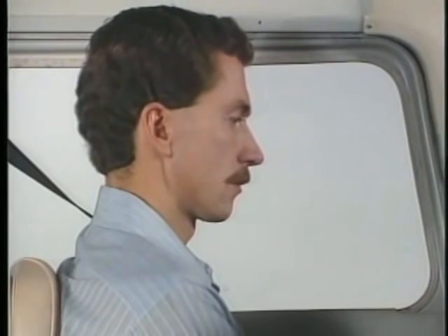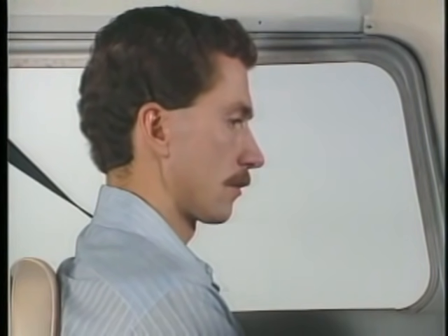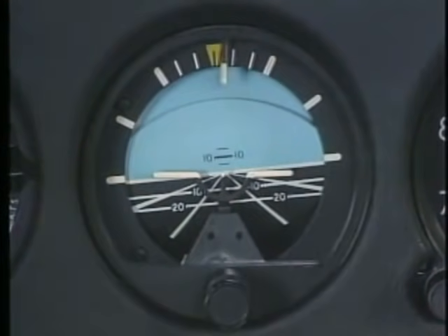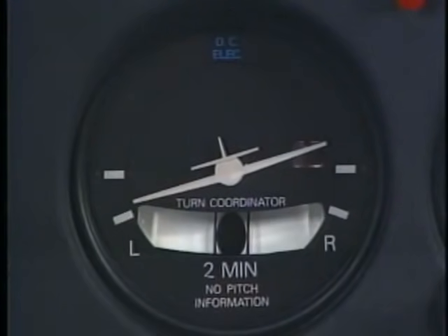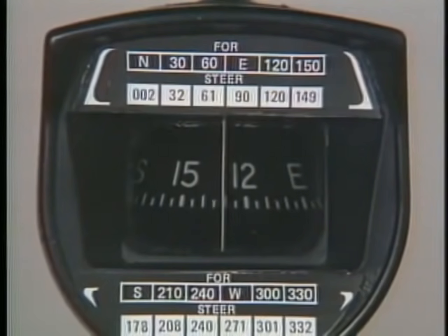Flight instruments, like all mechanical things, are subject to malfunctions. Therefore, you need to know alternate sources for pitch, bank, and heading information if the main sources are inoperative. For example, suppose you notice that your aircraft's attitude indicator is showing a 5-degree bank to the right. However, the heading indicator is not moving. The turn coordinator indicates a left turn, which is confirmed by the magnetic compass.